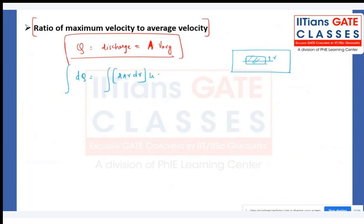If I integrate, summing all the small layers at distance r with thickness dr, I will get the complete discharge at that section. There is no doubt about it. But the good question is, what is the variation of u? We know the area is pi R square into u average, which will be equal to the discharge.